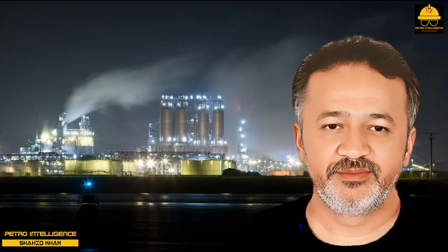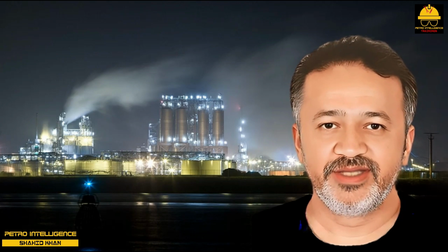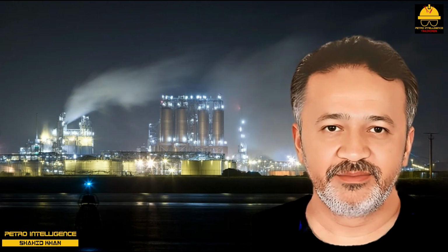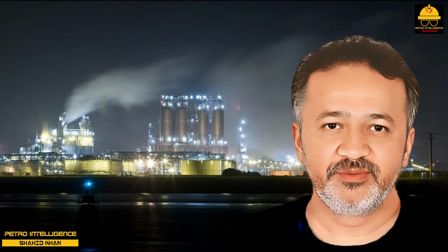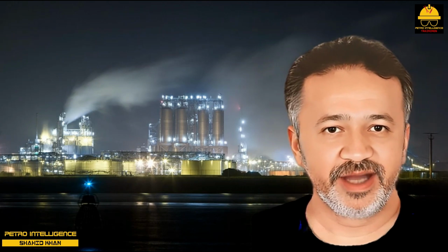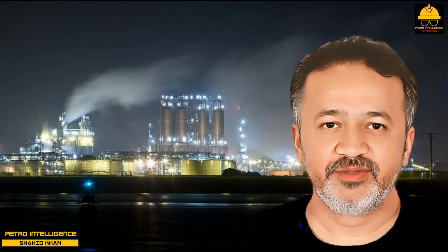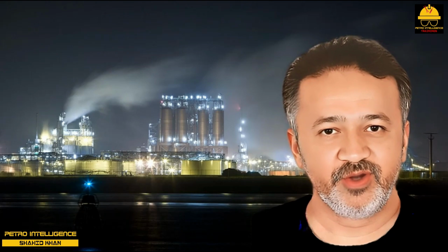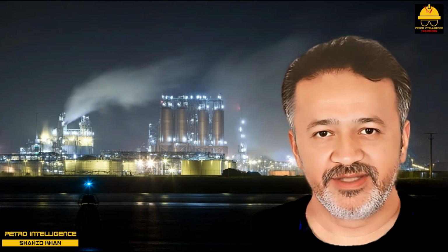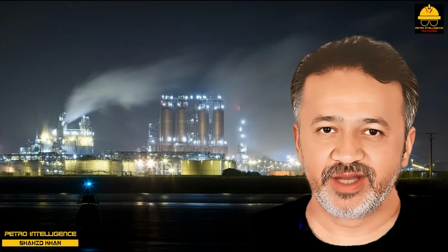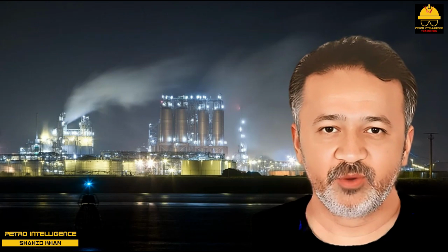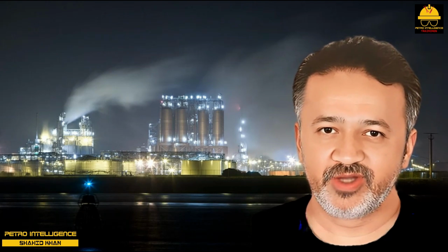Vortex shedding. When fluid flows at a 90 degree angle across a tube, it creates turbulence, which is called vortex shedding. The swirls created when a river flows across a tree stump is a common example. The swirls destroy the film resistance to heat transfer created by laminar layers of fluid surrounding the tube. Experience indicates that a shell side crossflow velocity of 3 to 5 feet per second is sufficient to obtain this benefit. To calculate the crossflow area, determine the open area between the tubes at the edge of the tube support baffles.